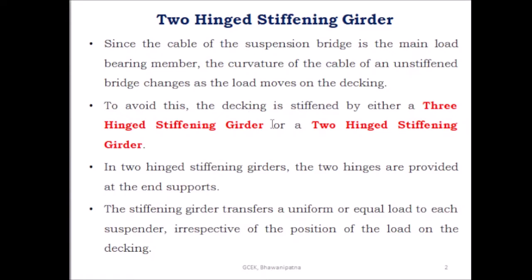Cable is the main load carrying member of a suspension bridge to transfer the load to the supports. It is a tension member capable of transmitting vertical loads horizontally by developing horizontal thrust through its shape. Therefore, the analysis of a cable involves the determination of stresses in the cable as well as the shape it would adapt under a given system of loads.